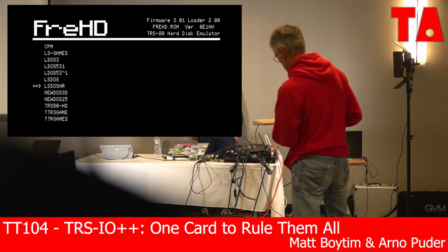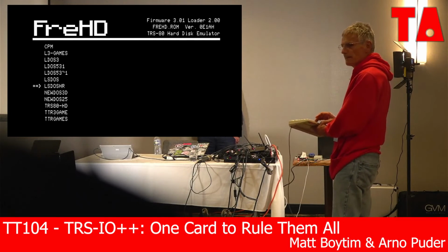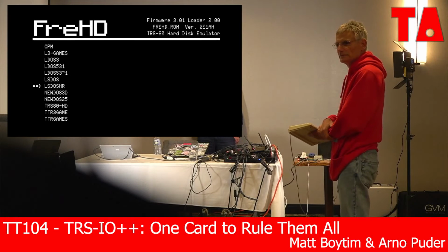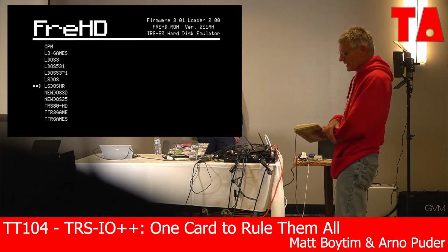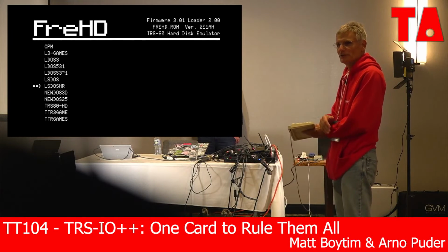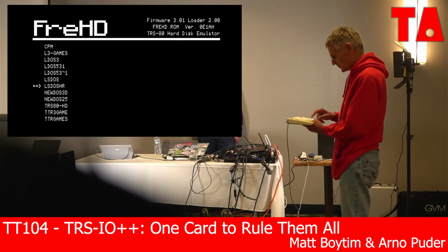If it's just a single bit, can't you attach it directly to the speaker? Because I've done that before at the FPGA, where I just take literally an output pin and hook it directly to the speaker. Well, that is what's happening, except the input is 8-bit audio. So how do you get it down? Yeah, so you do it with a noise shaping or noise shaper.